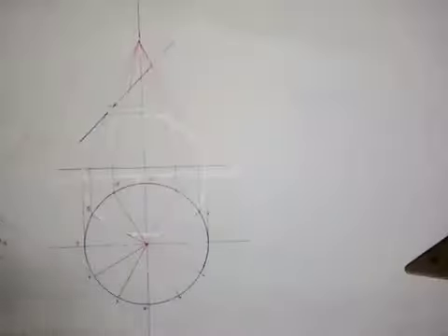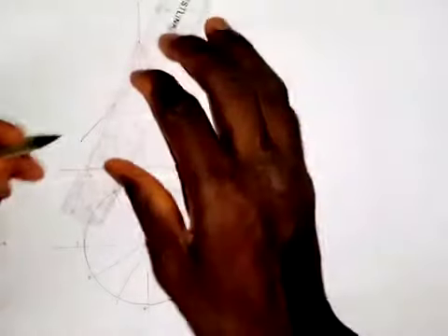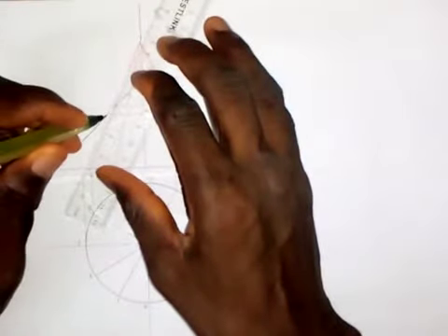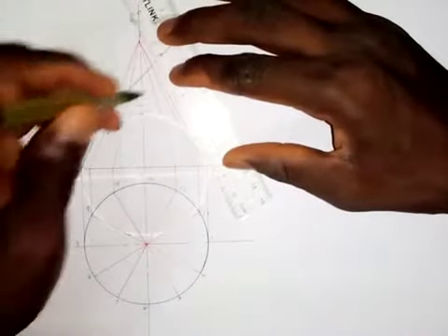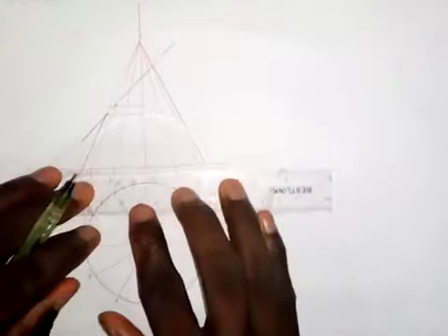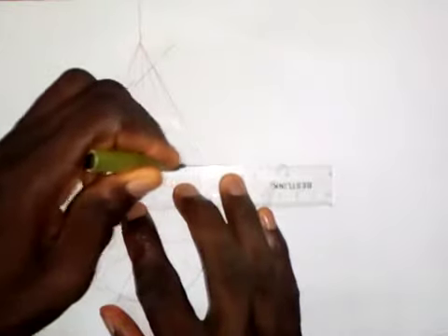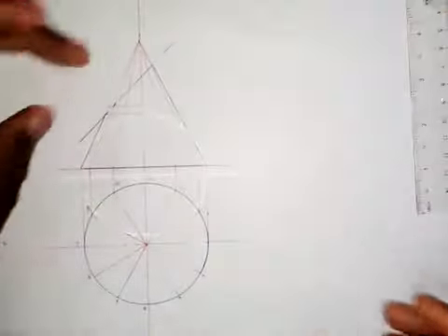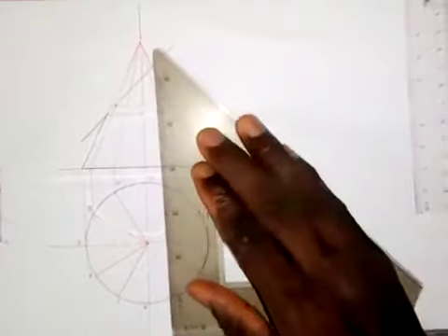Okay, so I put the cutting plane on it. The next thing I'm going to do is to make this side of the cone a thick line, and also this is a thick line like this, and this base is also a thick line like this. Okay, so complete plan. This part is cut off, so we are going to have a rough surface here in the plan. So what I need to do is to project a vertical line from this point,